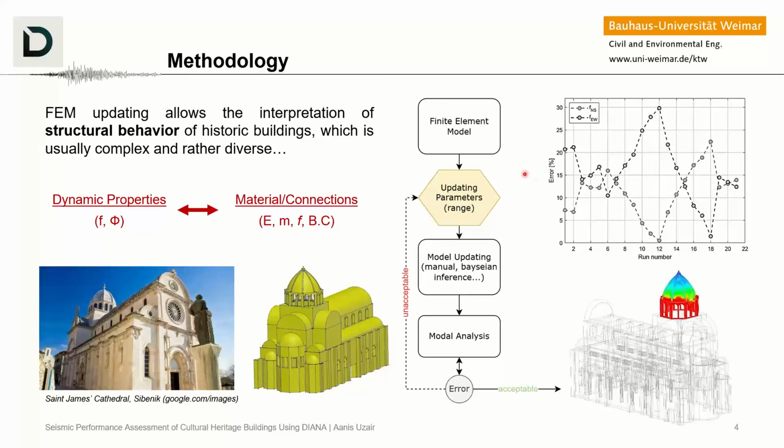So we are changing now the elastic modulus, the Poisson ratio, and the shear modulus. By doing this, we are constantly observing that the error keeps changing between different frequencies, and you would see sometimes they come very close to each other. Depending on what you are analyzing and how much error you can allow in the dynamic response, you say, okay, I pick either this set of material properties or this set or this set, where the error is minimum, and I use these material properties for any further analysis.